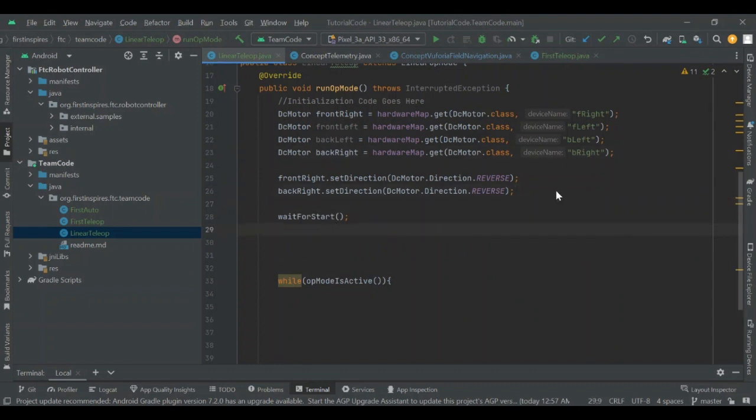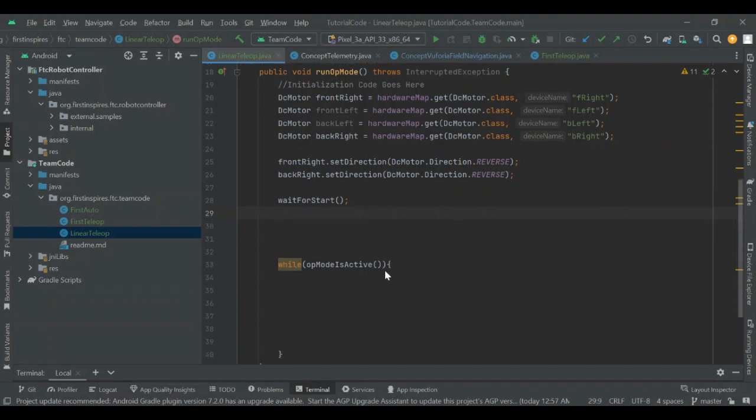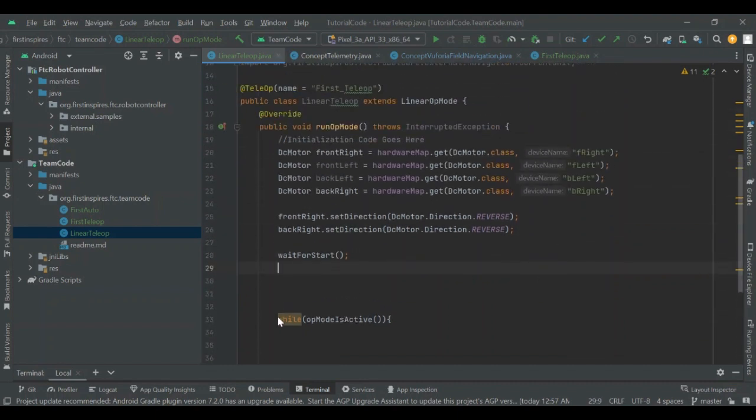So now I want to start with the 2 components of a tank drivetrain, which is the driving functionality and the turning functionality. So a tank drivetrain can either drive or turn. So we're going to be looking into that. For the tank drivetrain to be able to drive, it needs to be able to set the same power to each motor. So let's program the drive part.